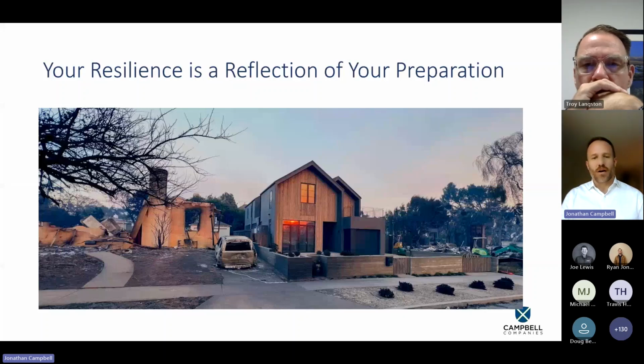It was designed to be fire resistant. It has a metal roof instead of asphalt shingles, that have tar and petroleum products on them. It has a concrete fence around it. It doesn't have vegetation or large trees around it. The wood they use on the outside, the windows that they use, the insulation that they use is all designed with the idea of helping prevent fire or limiting the risk of fire.